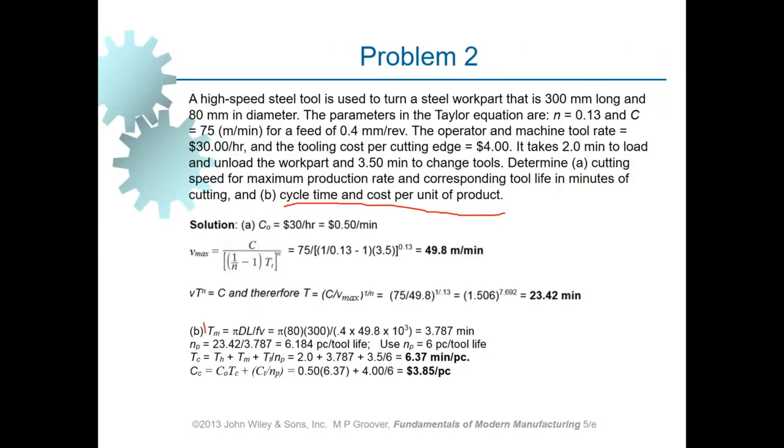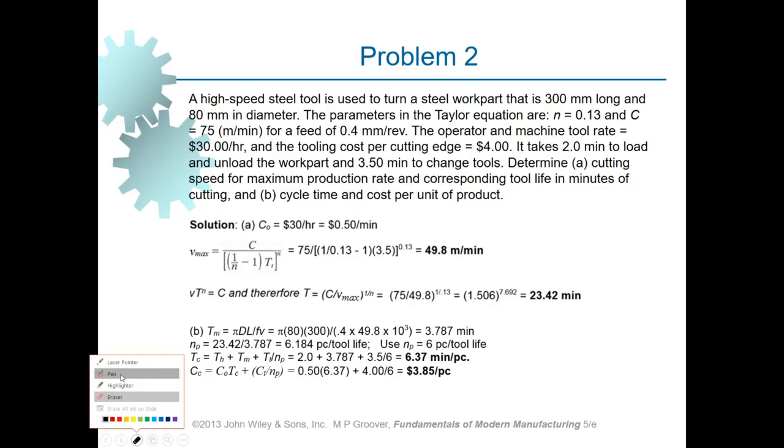Machining time equation, this equation is the one that was covered in the previous lectures, when we discussed different types of machining operations. In there, we also had this equation included. So we make use of the equation for, say, machining time for turning operations. In this equation, what we have is the diameter and also the length of the workpiece, and these are all given.